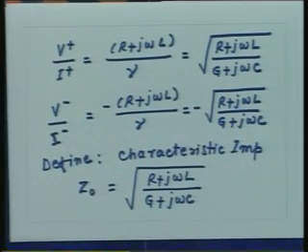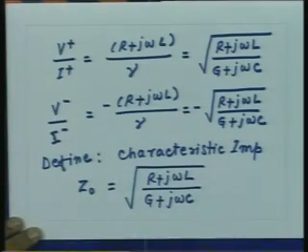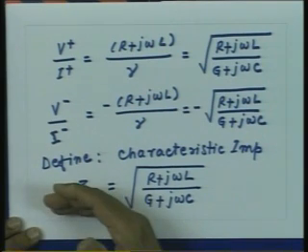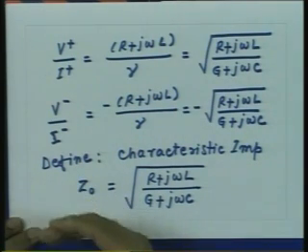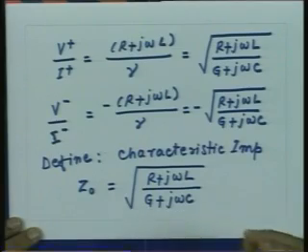And what does negative resistance represent? It tells you that the energy is not supplied, but rather energy is received. So, this essentially is telling you that if I look in the positive x direction, I will receive the energy, which makes sense in this case, because now the wave is travelling backwards, which essentially is carrying the energy backwards.